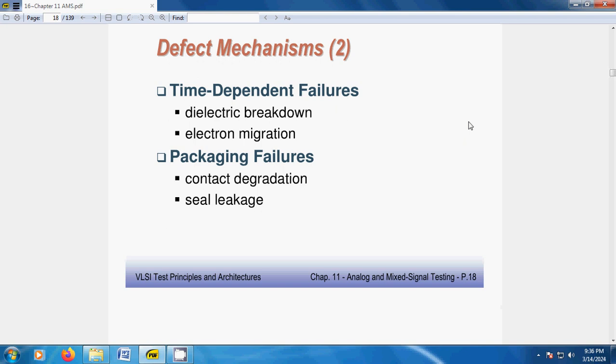The electrons do not travel smoothly within the particular channel. There will be a lot of collisions between the electrons and the material. Whenever an electron collides with the nearby materials or other electrons, it erodes the particular metal layer.